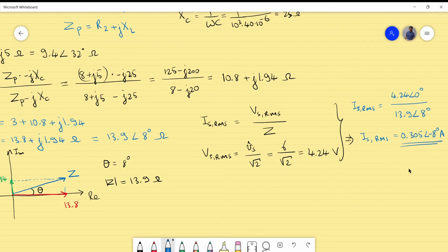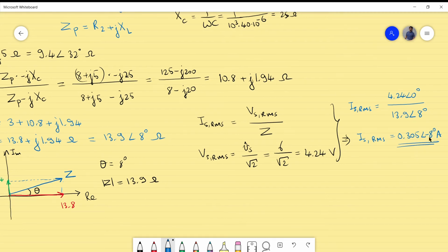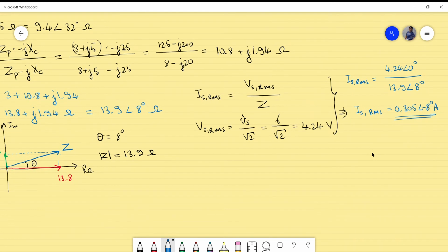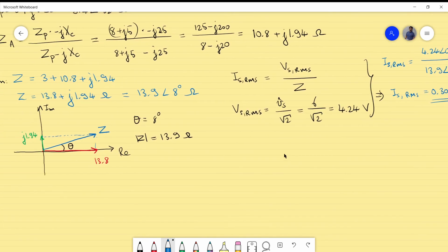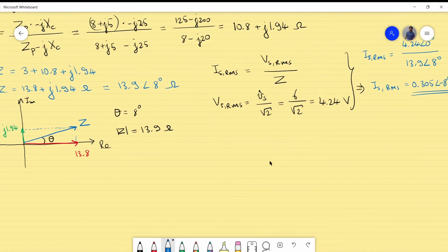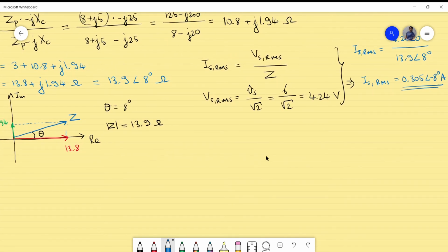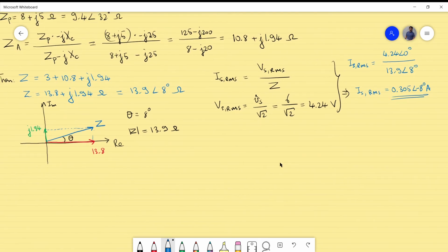So that's actually the situation, and you already know, because it is the minus sign for the phase, for the source, and you know it is a lagging. So this circuit is in effect an inductive circuit, so it is a lagging power factor. We already know that. Okay, now I can continue with the calculation of the powers. So that's actually the next step. So I will use this value and the expression for the impedance, total impedance. Then I will continue with the calculation. I will a little bit zoom it out so we can see the complete picture. So I will now continue with the powers.